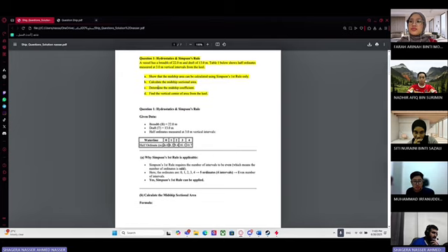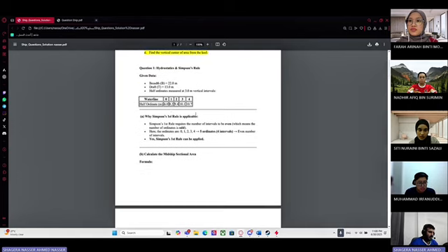For part A, show that the midship area can be calculated using Simpson's first rule only. To answer this question, you have to follow that Simpson's first rule requires the number of intervals to be even, which means the number of ordinates is odd.